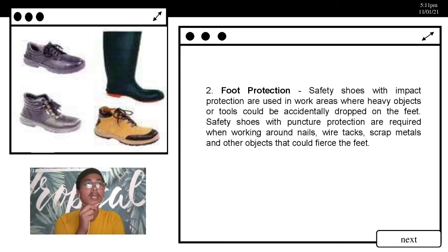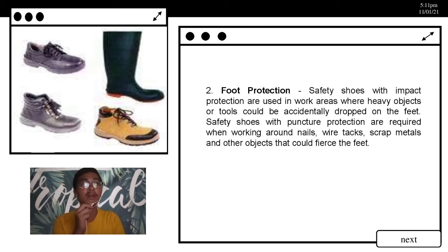So you choose safety footwear with the white rectangle and orange Greek letter omega if you are working in an industrial work environment that is really prone to accidental contact with live electrical conductors.